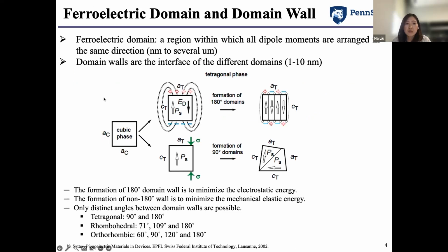the definition of the ferroelectric domain is those regions within which all the dipole moments, that means all the previously mentioned spontaneous polarizations, are arranged in the same direction. And this domain size ranges from several nanometers to several micrometers.